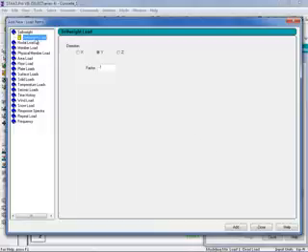The first load item that is automatically selected is the self-weight load. Now STAAD.Pro does have the ability to calculate the self-weight of the structure and then apply it as a uniformly distributed load if we specify this self-weight load item. When specifying our self-weight load, we need to enter a direction and a factor.